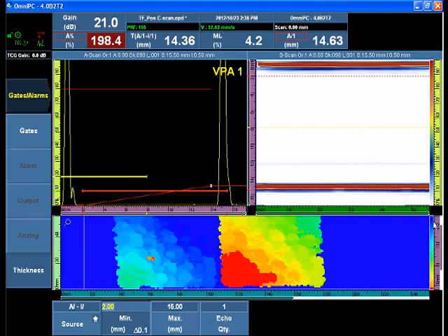On the C scan, we'll see 2 vertical bars, one describing the color palette and one describing the range for expected values associated with this. So in this inspection, the operator entered a thickness range of 2 to 15 millimeters, which would eliminate any readings outside that range from appearing in our statistics.